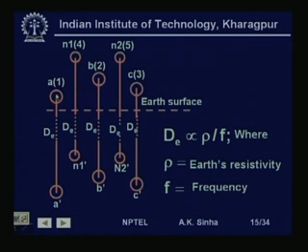Here we have 3 phase conductors A, B and C, and we have 2 earth conductors or ground wires, N1 and N2. For such a system, he proposed that the ground current flowing can be represented by a conductor A dash, which is directly below A in the ground, at a distance d from that conductor.